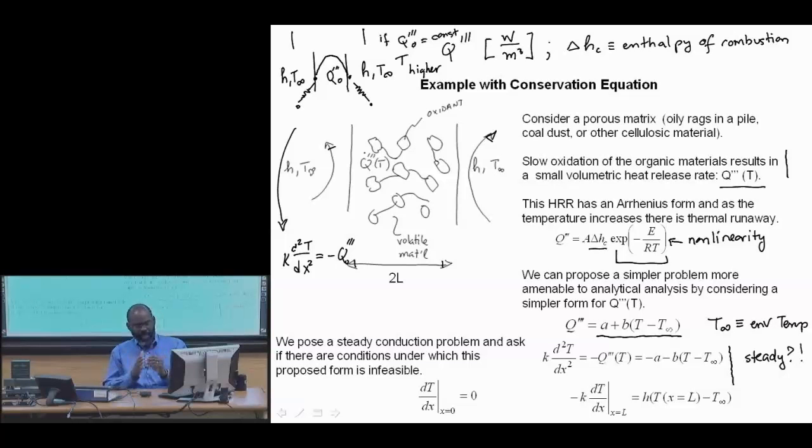If I have a constant heat release rate and there is a steady solution, and I increase the extent of that system, I would have higher temperatures because of the points that we discussed. But now, if that heat release rate is temperature dependent in such a way that it increases with temperature, I get a much larger increase in temperature because my rate of energy generation is larger than it was in the smaller system. Okay, I'm maybe beating an obvious point.